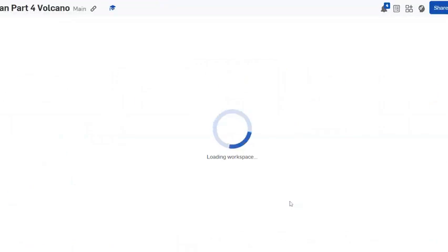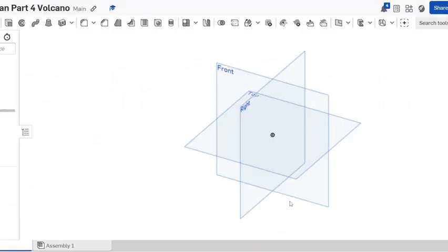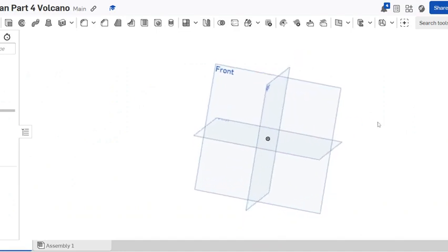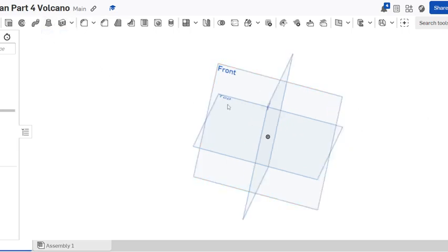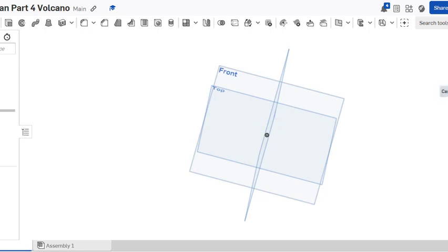All right, here we go. This is fun. We're going to start with a couple different things. So for this one, if you think about it, when we're building stuff, we want to build it on the top plane and then pull it up. We're going to extrude and pull it up and loft it. We're going to use this cool thing right here called the loft button. All right, so let's get started.